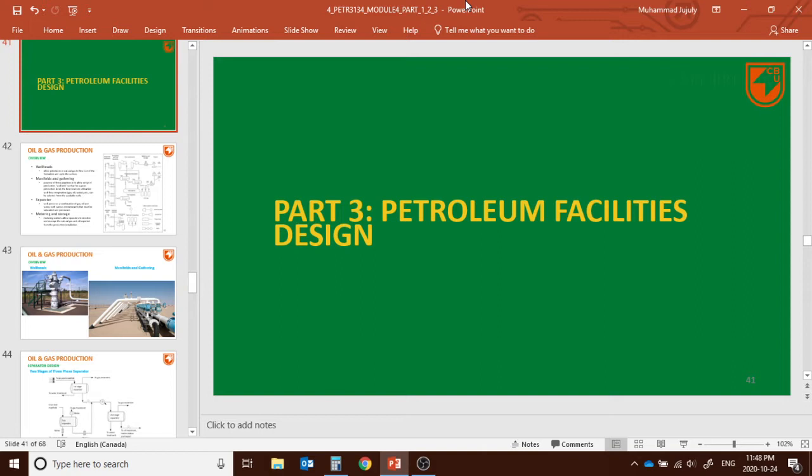So at part 1, we have learned the basic fluid mechanics theory, especially Bernoulli's law, and how we can apply it to calculate the pipe head loss. In part 2, we learned more specifically about oil and gas pipelines, especially for crude oil and refined oils. What types of equation should we use for the pipeline head loss, and how can we actually calculate the pipeline head loss using